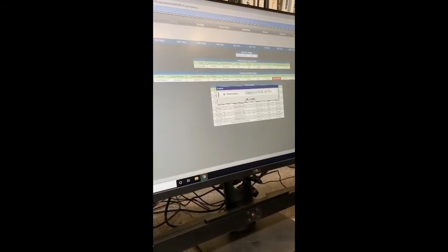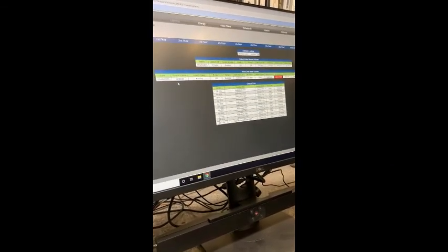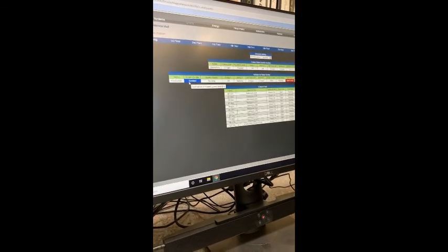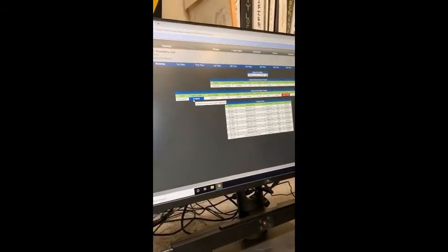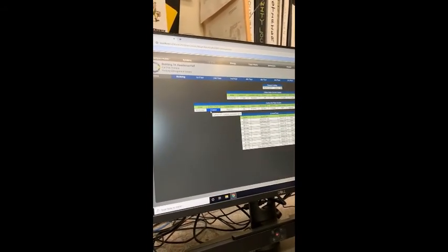Here, I'm just going to put it to 15 minutes, and I overrode it. Once it goes out of that 15 minutes, what will it go back to? It'll go back to whatever it was normally. When you're overriding a point, that is a point that has something else in the code writing into it, and you're taking priority over that input. So when it releases, it would be whatever's writing into it at that point. It doesn't matter what it was; it only matters what's writing into it at that time.